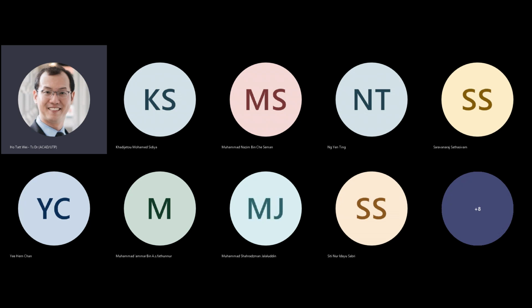So I'm basically reviewing a lot of material very quickly to show you first that a two-input multiplexer can be implemented as a cascade of an AND gate followed by an OR gate. This is called the sum of products, right? You are summing, these are all functions associated with plus, and then the products are associated with AND gates. And any sum of products, SOP, can be implemented equivalently as a two-stage NAND, a two-layer NAND.